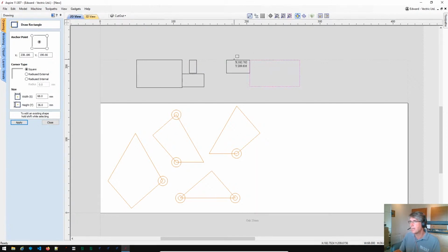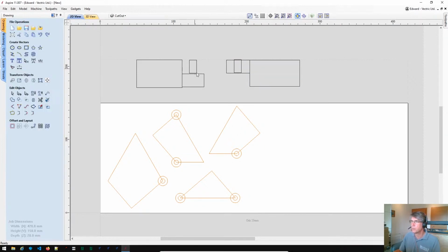They're going to have that piece and that piece. This is their main bit, and they're going to have a matching drill hole through which that peg will insert. So these parts, which I'm going to call the female parts, are actually going to be cut from the wrong side. If you think about it, we need to cut them from this side, and that means we're going to need to flip the parts, otherwise we're going to end up with mirror images by accident.